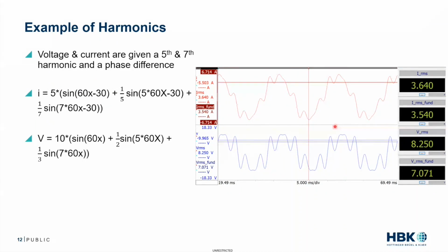So we have to ask ourselves, which one am I interested in? Do I want the one without any harmonics? Do I want the one with the harmonics? So that's the question we need to ask: I want the RMS value of what? So I'm leading to something which is the switching frequencies. But this is a question to ask, and this just introduces this basic idea that not all RMS values are created equal. It depends what our frequency range is.